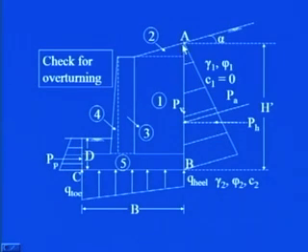And then you can see how this active pressure is getting generated. Its line of action is parallel to the inclination of this backfill. So, you can see here this is your active force which is acting. It has a horizontal component Ph and a vertical component Pv. Again, in this area the passive condition is developed, so passive pressure and subsequently passive force will be generated in this manner over the depth d.